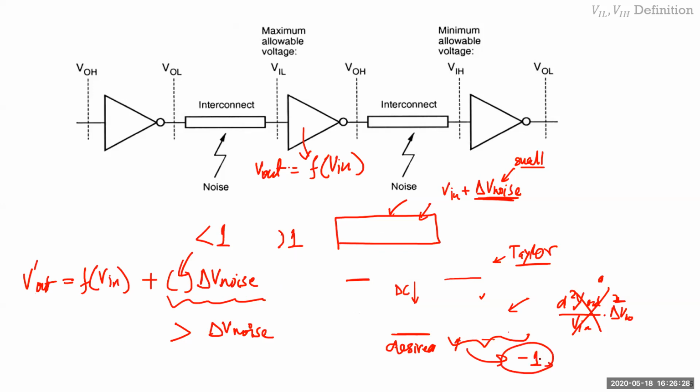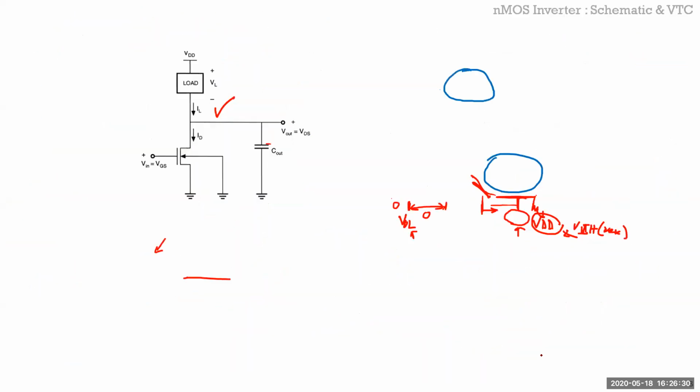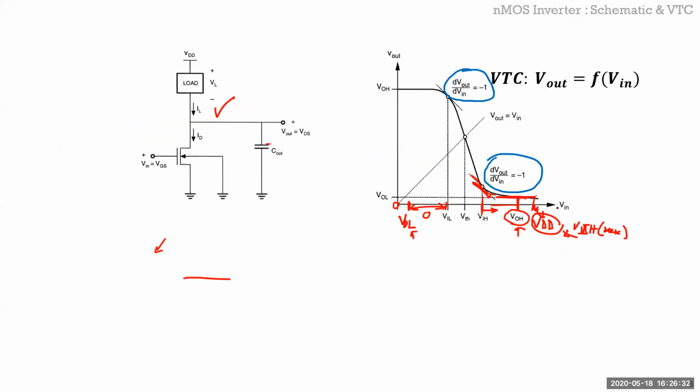So if I go back to the derivative curves here, you say, okay, this derivative starts at 0, 0.1, 0.2, 0.3, 0.9, minus 1. You stop here and say, this is my margin. That means this whole range, the input to this gate will be considered low and the output will not change much, and it will not magnify the noise.